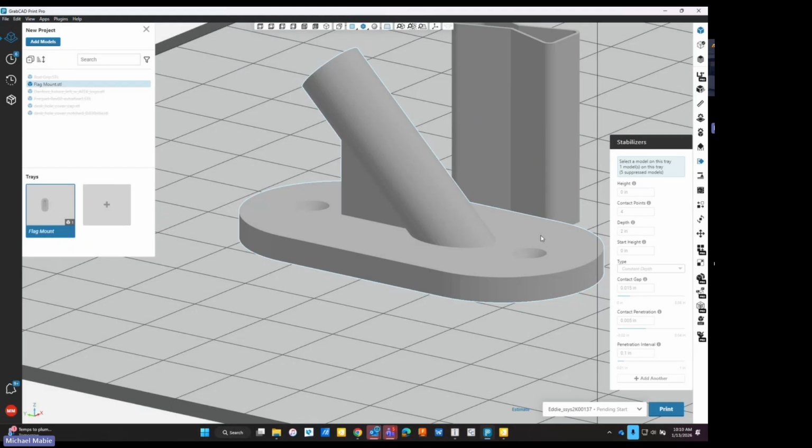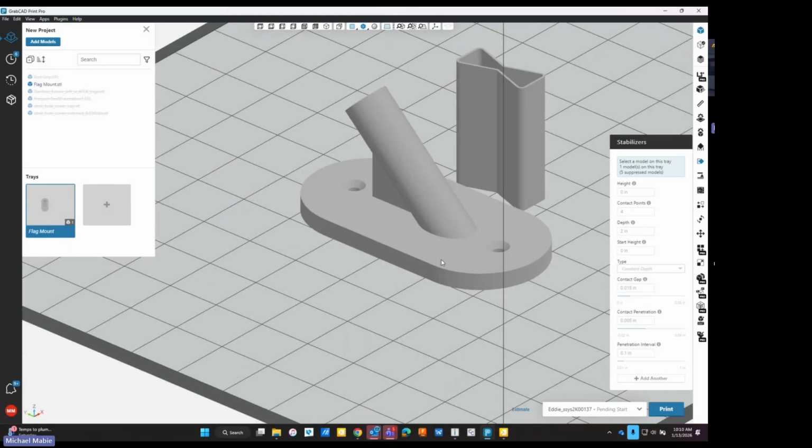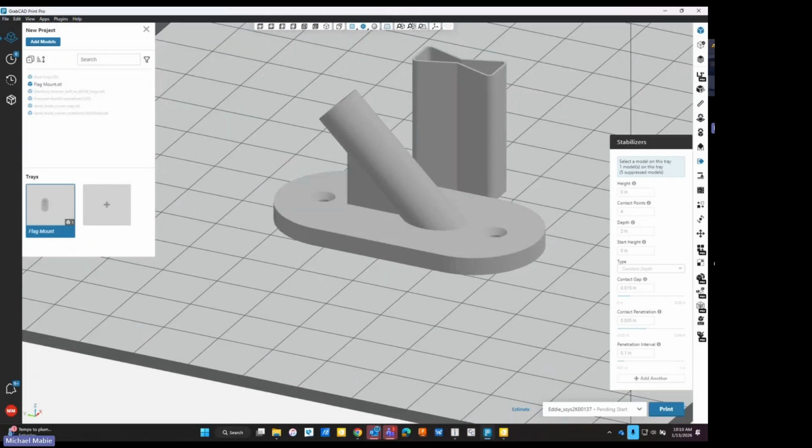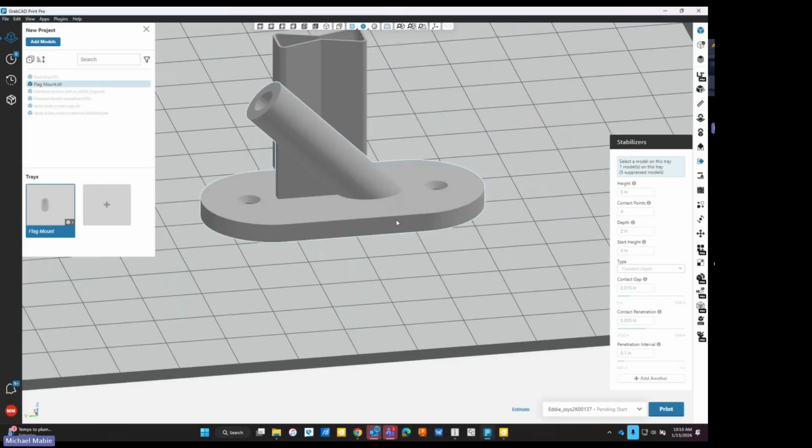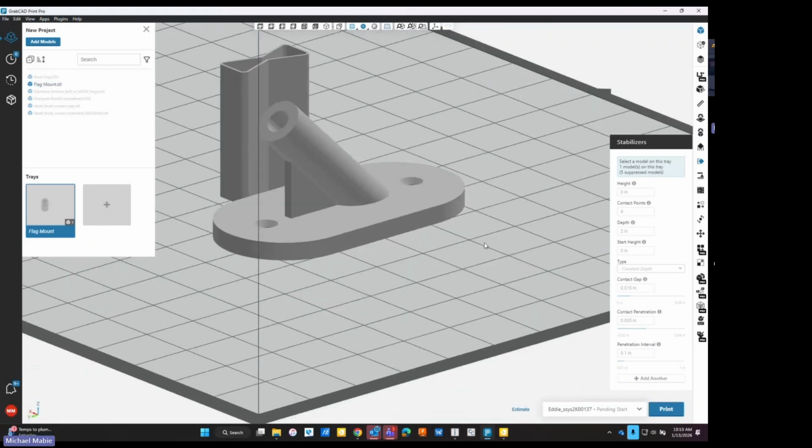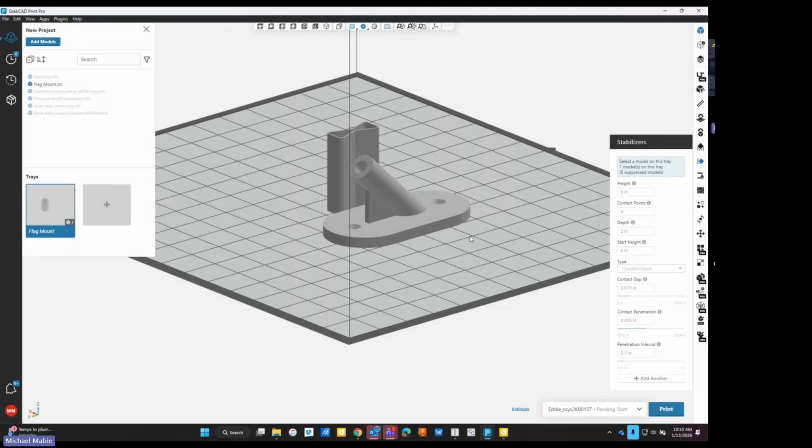So if you've designed the part and you know exactly what all the wall thicknesses are, you want to look at the average. If it is a part that you did not design, then I would highly recommend you use that measure function and measure in a couple different areas. Now, it also is going to matter depending on your build orientation.